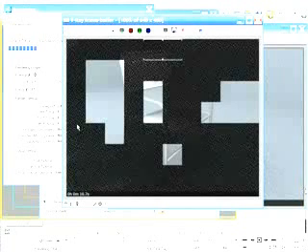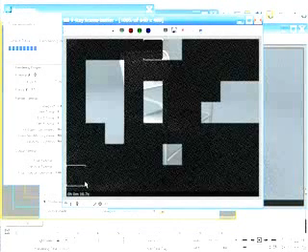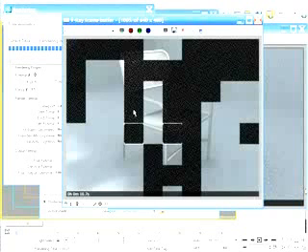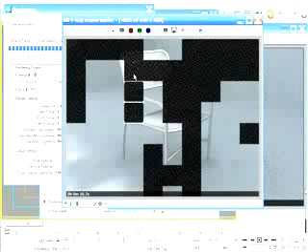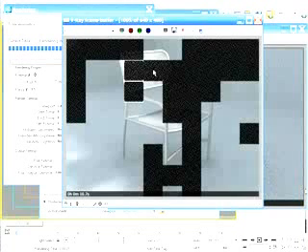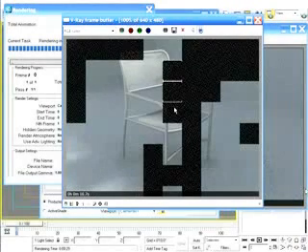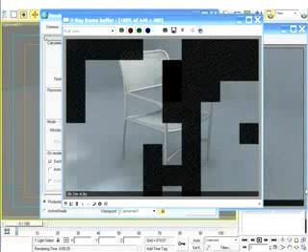What makes it so great is that unlike a render region, which obviously allows you to specify a certain area of your screen to render by itself, this feature essentially lets you define multiple render regions. Not literally, but by moving the mouse from one point in your rendering to the next, you're in a sense defining a region one bucket at a time. This can come in very handy when you have more than one specific area of your rendering that you're trying to see rendered before others, which might be something you would want to do if you're conducting test renders or to simply ensure that you know as early as possible whether or not your problem areas in your scene will render okay. The longer your renderings take, the more this particular feature becomes a handy one.